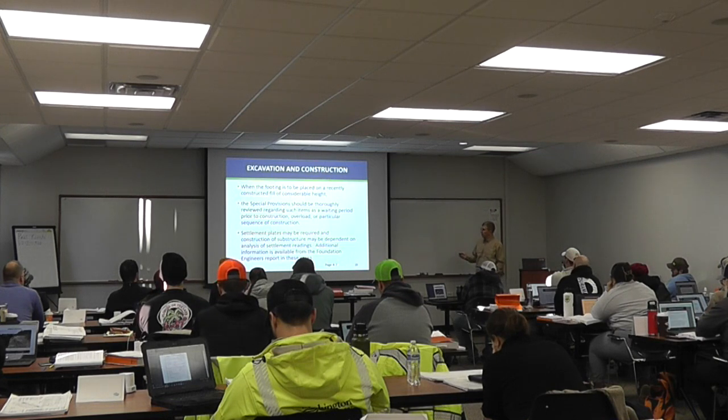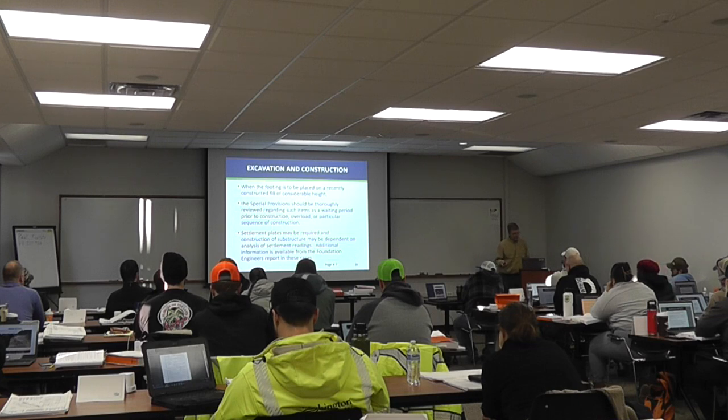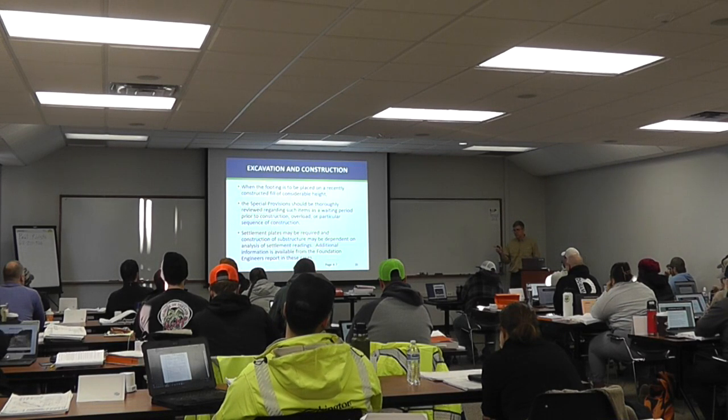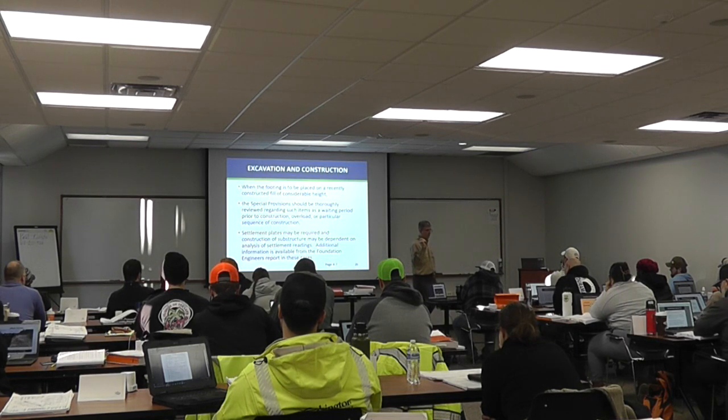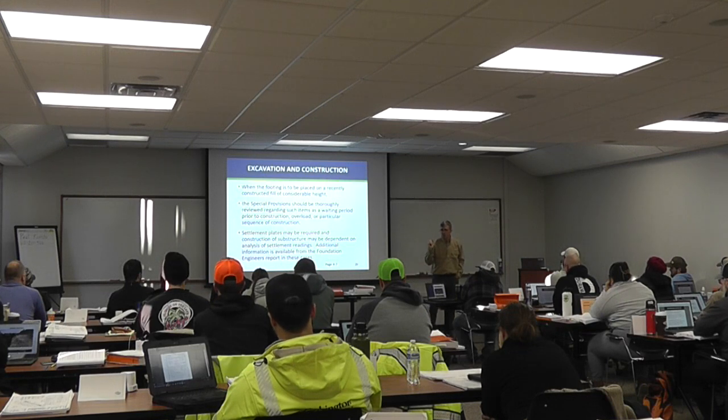So when the footing is to be placed on a recently constructed fill, we need to think, is there a waiting period? Even though we don't have spread footings on our bridge, there is a waiting period. Anybody remember from the front sheet and what Andy talked about, what's our waiting period before we can start building? 72 hours on this one.